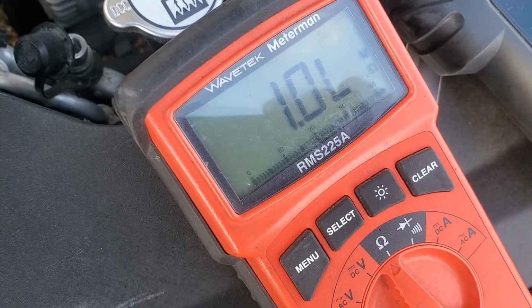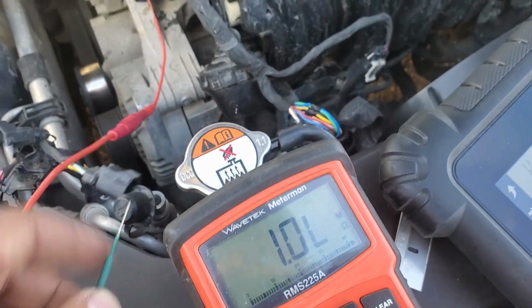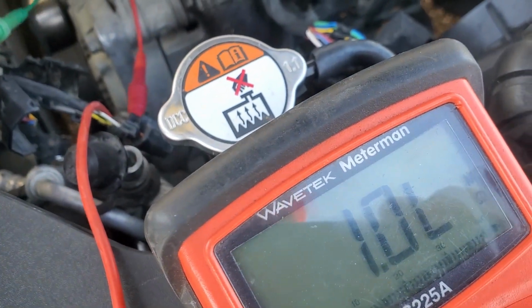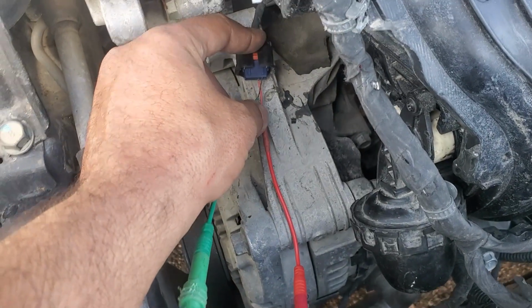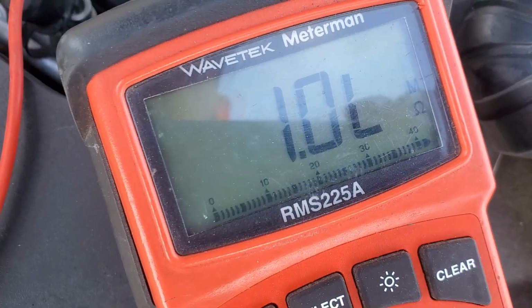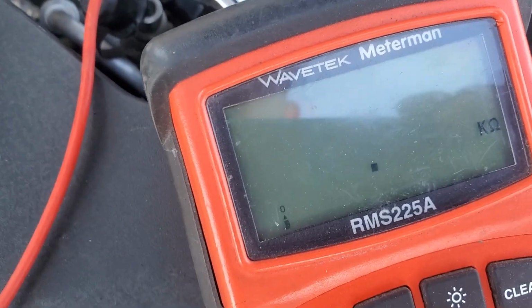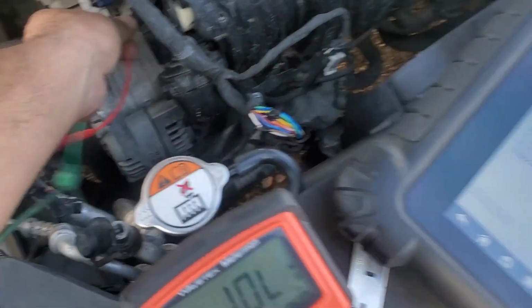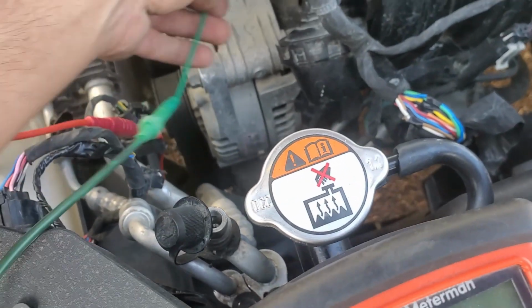The weird thing is that the test is talking about the sensors, replace the sensors, but again, how likely is it that 2 sensors went bad, and I don't see any connection between them when it comes to the diagram. I am probing on both pins, touching just to make sure that it's working. Yeah, I'm probing on the other pin. We don't have anything, so it's not shorted to each other. How about the signal short to ground? So they're not short to ground.